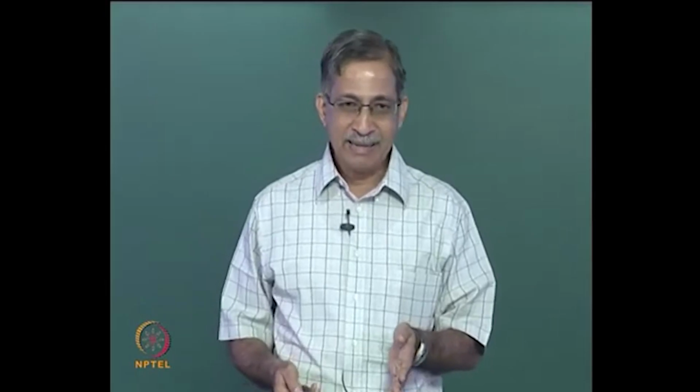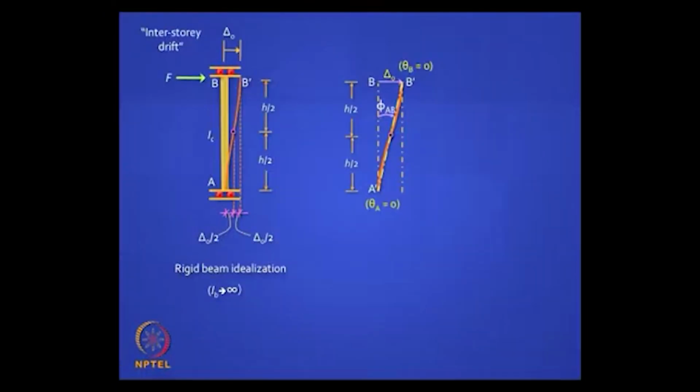So now this will give you a better idea of a symmetry in that frame, and of course it is unstable, so the rest of the building helps in propping it through. So this is the deflected shape, and we talk about a chord rotation phi AB, which is clockwise and which is nothing but delta naught divided by h.